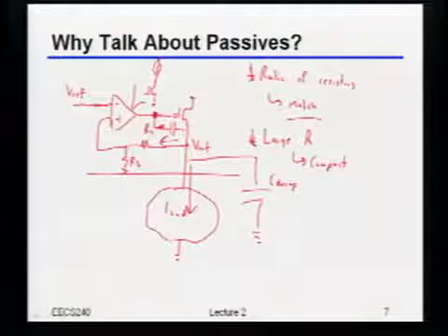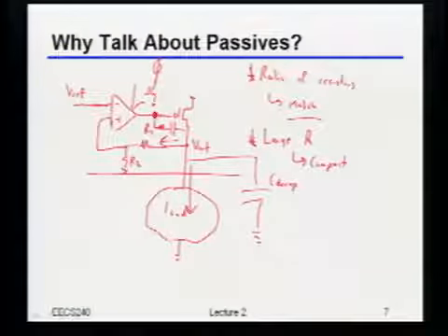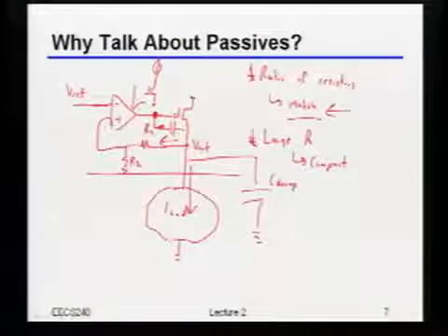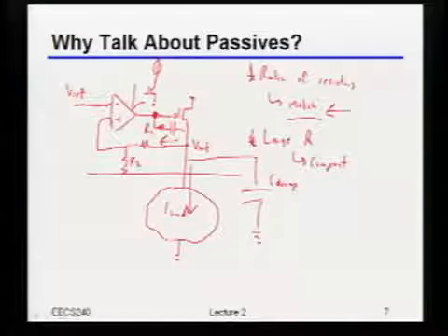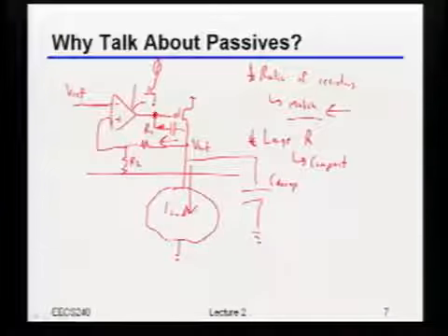Now again, for that capacitor, what might I care about? The ratio to the load. Yeah, I care about the ratio of that cap to the load. So again, I care about matching. I probably, again, may want something reasonably large in a small area, so again I care about density. There's one other thing here that I claim is sort of interesting that we haven't exactly touched on yet.